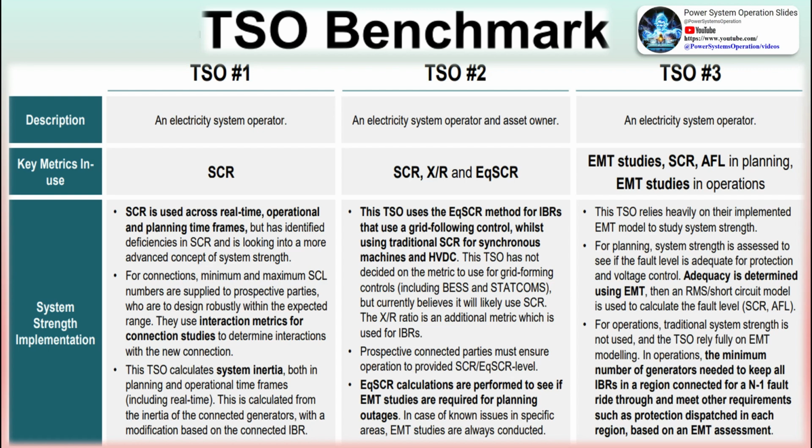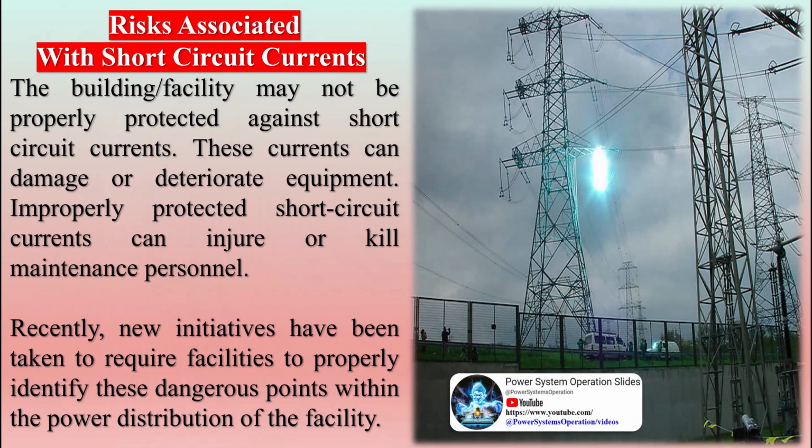Factors affecting the accuracy of short-circuit fault studies. IEEE Std. 399 stated that there are some factors affecting the accuracy in a short-circuit study. They are system configuration, system impedance, neutral grounding, pre-fault system loads and shunts, mutual coupling and zero sequence, phase shifts and delta-Y transformer banks.